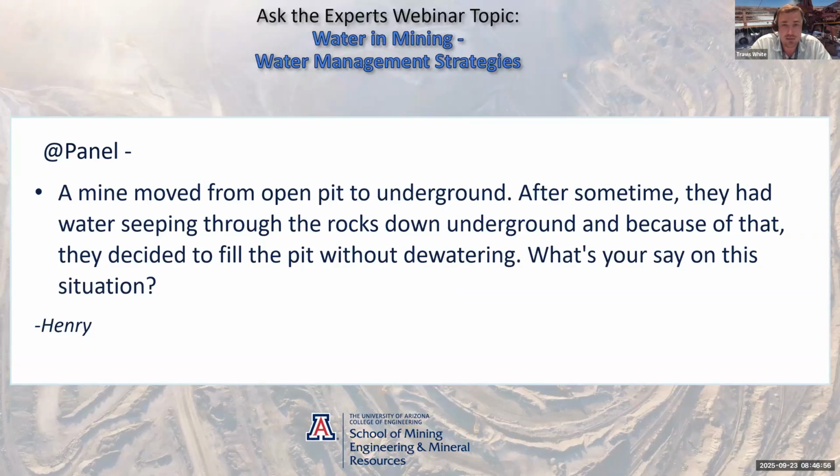That being said, there are certain scenarios where backfilling a pit can be done properly and can actually reduce the risk. If you geoengineer your backfill where you have some impermeable layer at the base, like fine tailings, for example, with either penstocks or interception wells that you can use to manage the volume of water stored in the backfill, that can actually be beneficial.